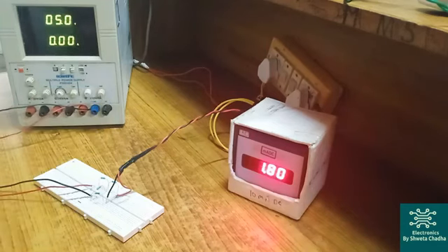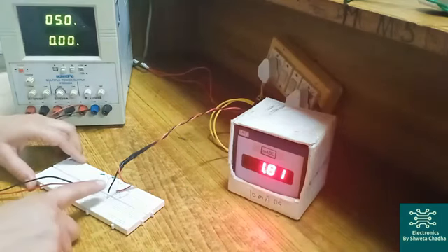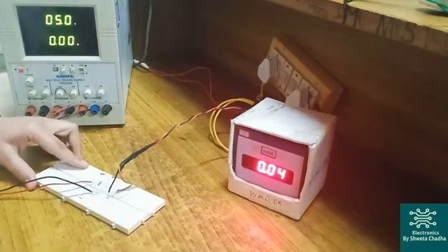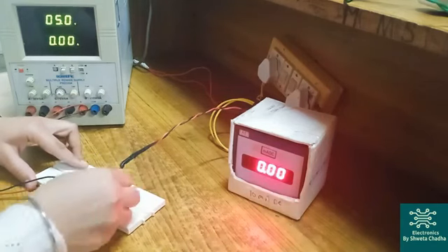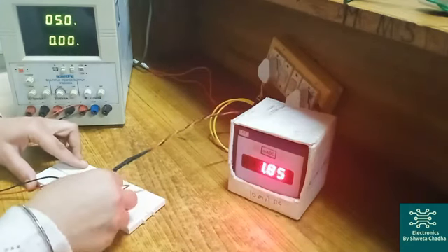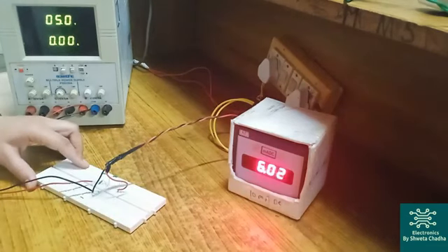So we have got 1.8 milliampere IL, the first circuit diagram. Second circuit diagram is remove RL. So this is our RL 1 kilo ohm. Remove RL and calculate short circuit current. So that means we are now supposed to calculate the current IN, that is Norton current. So the Norton current comes out to be around 6 milliampere.